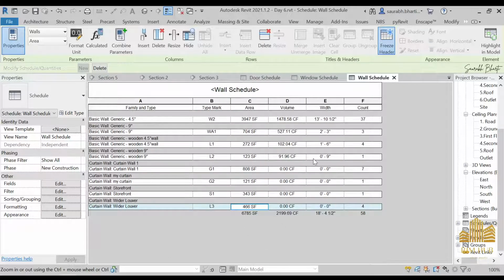Done. So these are the required things that we have in our project. And now as you can see, everything has been provided by Revit. So there's some bug in Revit 2021 by which we cannot see a few of the things every time in this scheduling section. So as you can see, we have this 58 division in our wall, and then this width of wall, then circumference and area, and these are the types of wall, and this is the name of the wall.